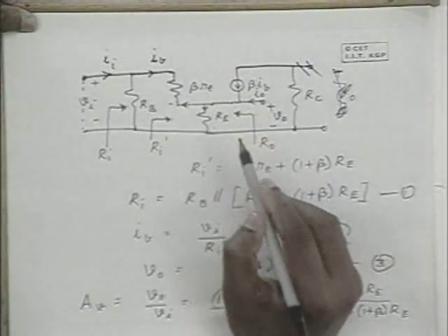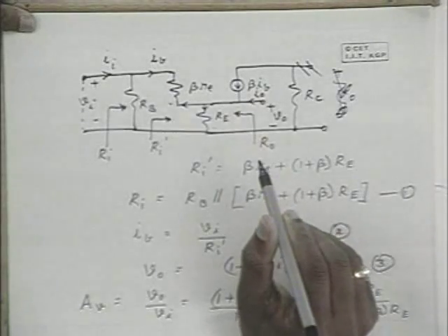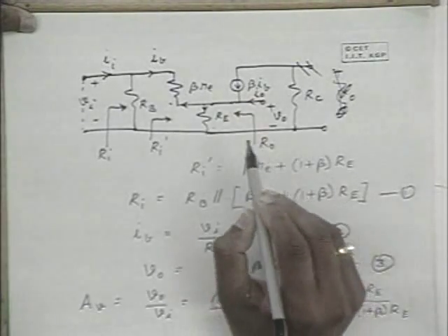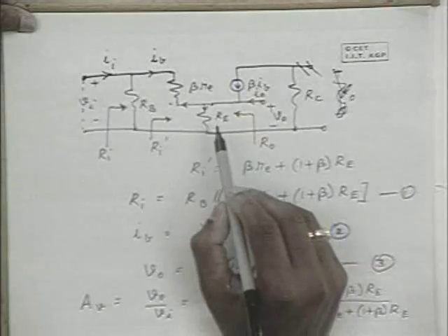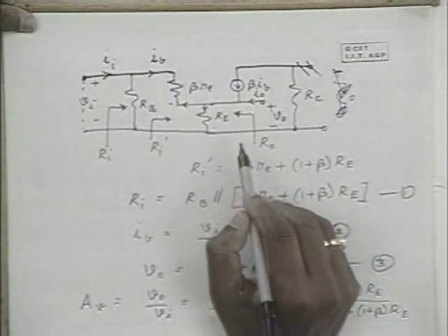Hence it offers you a very low output impedance. So as a result of this, we can use an emitter follower circuit to drive low impedance loads like loudspeakers in a public addressing system and motors. Any questions on the emitter follower?